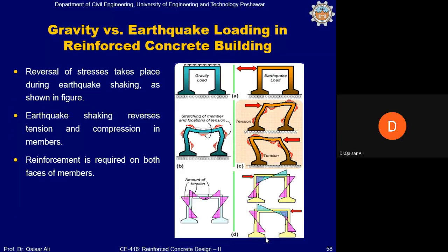Okay, that means the reduction should be included at design time. Yes. There are two types of concrete. In reinforced concrete, creep is not a severe problem. It is a problem, but not out of control. However, in pre-stressed concrete, I hope you know pre-stressed concrete, creep shall be minimized because creep is associated with the pre-stressing forces.